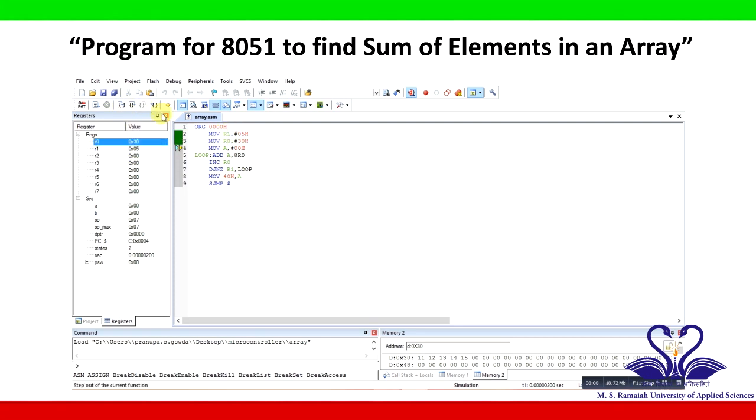So the next step is executed, which means MOV R0, #30H. So #30H means that it is immediate data. 30H is moved to R0. So you can see R0 is loaded with 30H. Then as a third step, it is MOV A, #00. So the accumulator is loaded with 0 value.